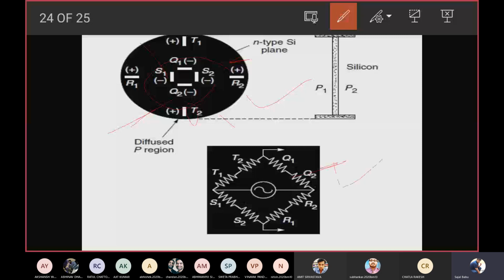Okay. So the reason why we connected the two resistors in cascade in one arm is to reduce the temperature effect, or you can call it temperature compensation. The remaining everything will be the same here. So this is also going to convert the force into changing resistance, because the semiconductors are going to have some resistance there, and they are going to do the same thing.